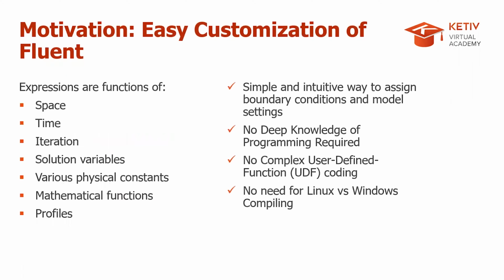Now, why do we need Fluent Expressions? Why are we talking about it, right? For those of you who are not familiar with using expressions, let me just briefly define them. They are uniform and non-uniform functions of spatial coordinates, time, iteration, solution variables, different physical constants, and perhaps profiles that you want to assign in your CFD setup. They're simple and intuitive to use. They're just like mathematical expressions. So even if you're new to the concept of expressions, it'll be pretty easy for you to get up to speed on it.